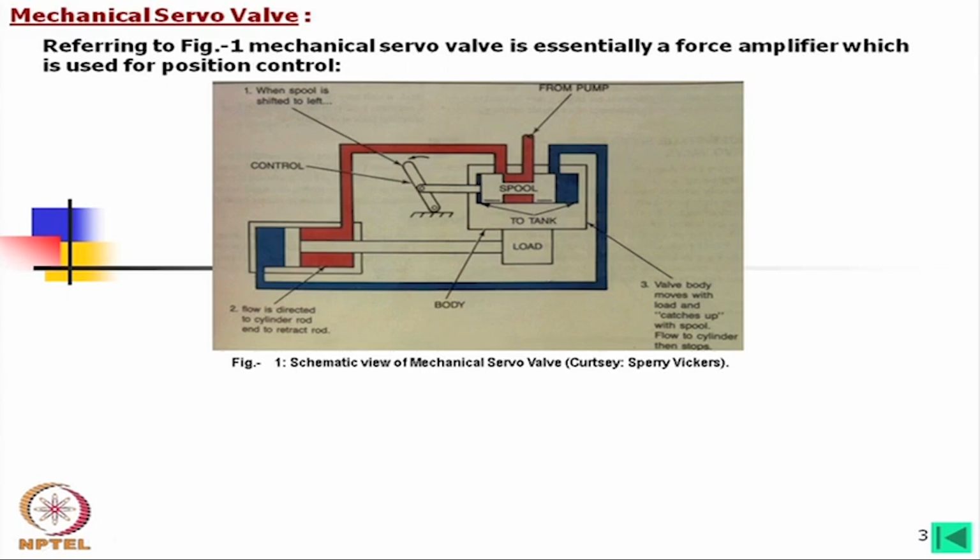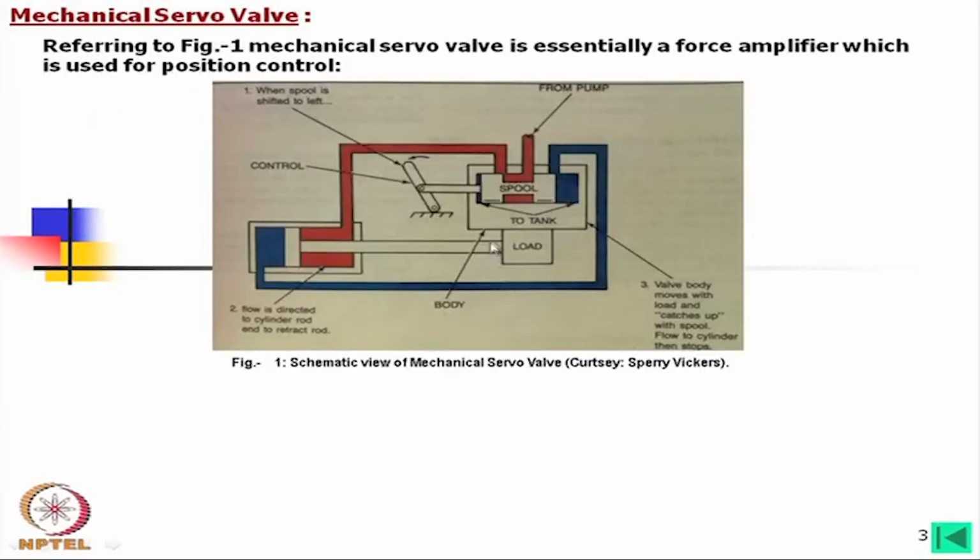This principle is used in many places, including copying machines, such as copying on a lathe. In the copying process, some hydromechanical servo valve is used. For example, if this is fitted over the template, following this template, the feed is through the template and automatically this will move.